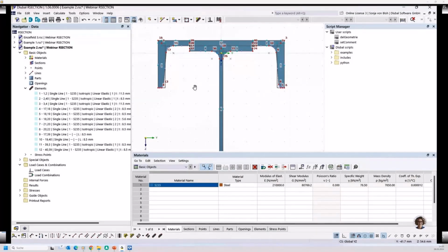The standards Eurocode 3 and Eurocode 9 only provide rules for the generation of subpanels for constant element thicknesses. Therefore, subpanels are only generated if the boundary lines of the part are equal to the element edges and if no other part is connected.